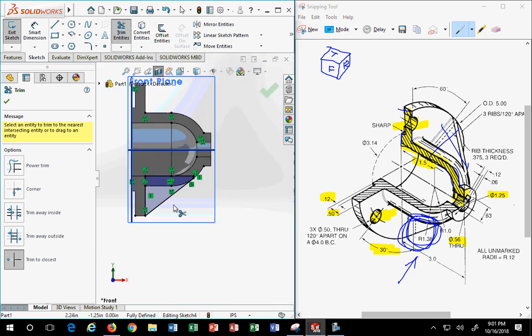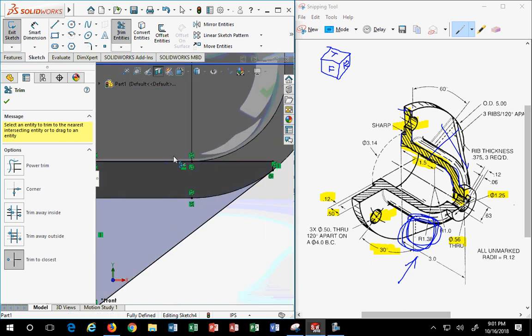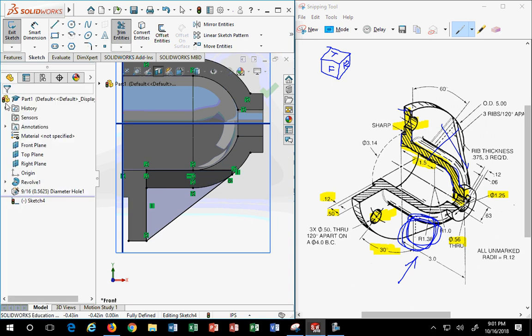You're going to ask me, well, okay, you've got this attached to this inside wall. Now I'm going to hit OK. You have this attached to the inside wall. Why? If I ever change that inside diameter, what's my rib going to do? Update with it. Yeah. Just like I proved before when I was doing the blade. Because the way the blade was drawn, when I change elements on the blade, it just expands and contracts and changes everything. Ditto for here.